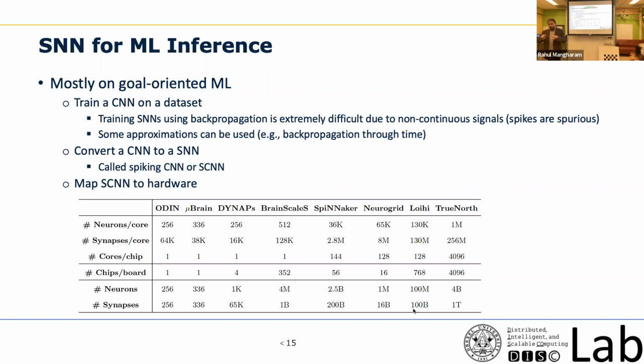You have cores, just like in biology. In biology, there are local and global synapses. Local synapses are local connectivity where you have dense connections, and global synapses are long distance synapses, which are not so heavily connected. So the global ones you can reconnect? Exactly. Global ones are typically implemented as a time-shared, time-multiplexed interconnect. So you can transfer anything, and with a small piece of information on which neuron it should go to, you should be able to do it.